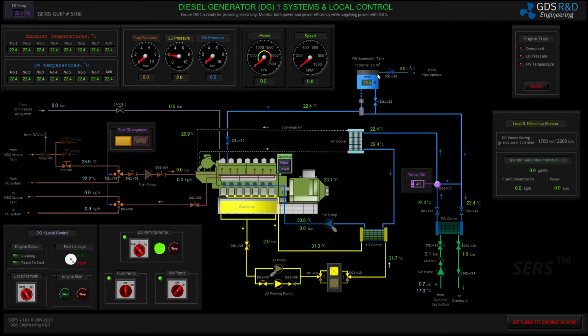I continue lining up freshwater system. These are the inlet and outlet valves of freshwater cooling. I won't be able to operate freshwater pump unless I start my diesel generator, because this is an attached pump.